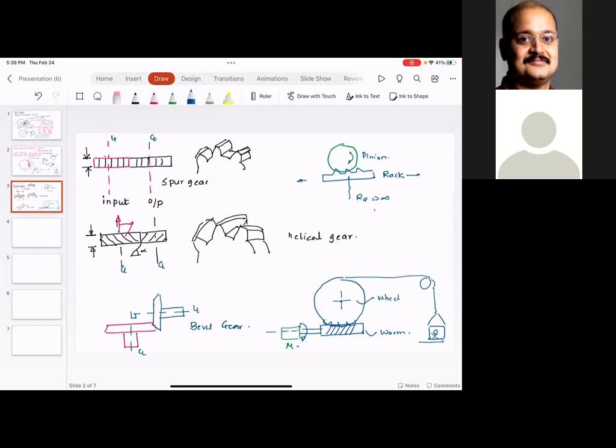When we talk about spur gear design or helical gear design, I'll take an example wherein you design the gear train, you design the housing, and then I will tell you how to select the oil for that particular power transmission. Please understand, oil is a two-edged sword. If the oil is too viscous, rather than decreasing the coefficient of friction, it increases it. In other words, it increases the power needed to transmit.